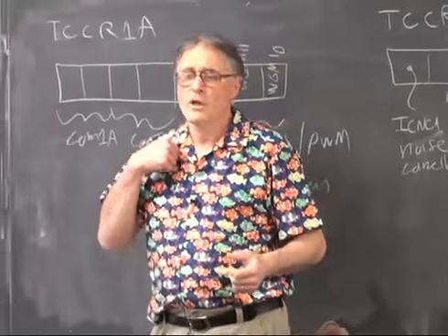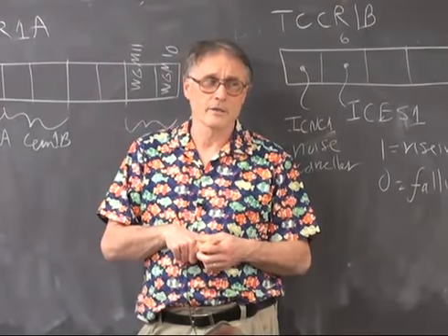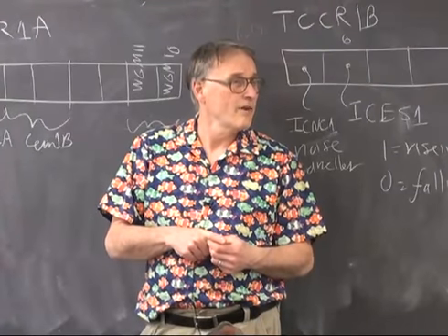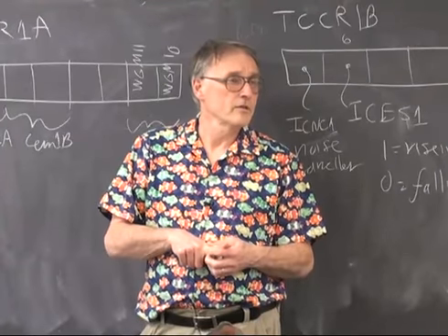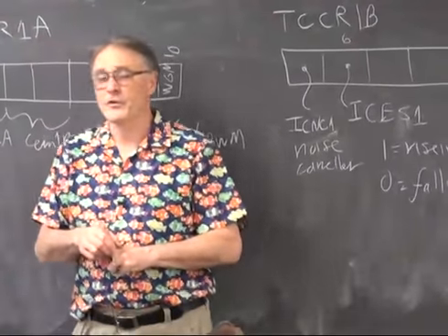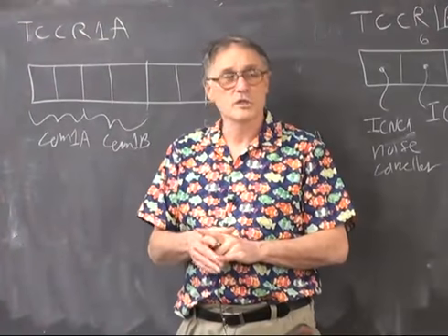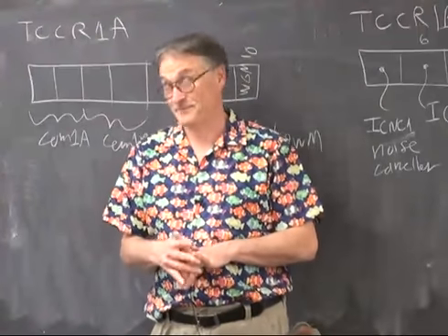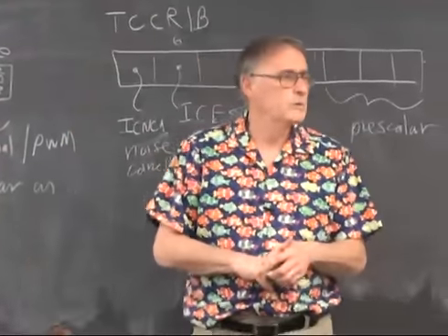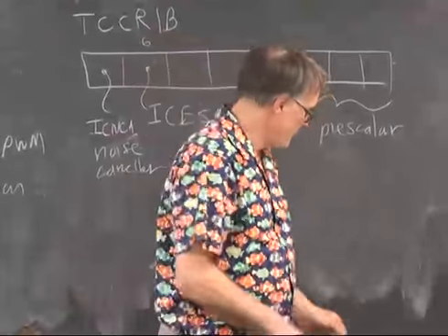So you can go to 2.4, 5 gigahertz. I think there's an unregulated band. Anybody know for sure? I think there's an unregulated communication band at 5. They use it on Wi-Fi now for a second. 5.8. Now it's also used for phones. And then above that, if you can figure out how to generate it, you can do almost anything you want above 10 gigahertz, as long as you stay out of the police radar bands. That's a bad thing to do, police radar band. So if you're going to transmit, think carefully how you're going to do it. Okay.